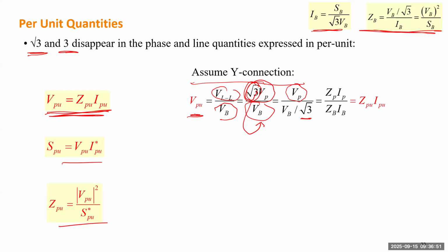The phase voltage is equal to the phase impedance multiplied by the phase current. And this denominator is basically just the base for one phase, which is equal to the product of the impedance and the current for the base value. For the last item, immediately you get per unit impedance and per unit current. So that's done. That proves this formula will always be true in a three-phase system.